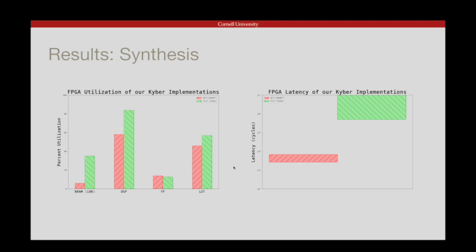The second key point to notice is that the flip-flop utilization for the overall design hardware is actually less than just having the NTT algorithms in hardware. This is surprising, but becomes clear once we consider the optimizations present. When performing just the NTT algorithms, we can optimize more heavily, resulting in large flip-flop usage for unrolling and pipelining intermediate results. However, with the entire design, many fewer optimizations are present, allowing for flip-flops to be reused over many cycles, resulting in an overall lower flip-flop utilization.